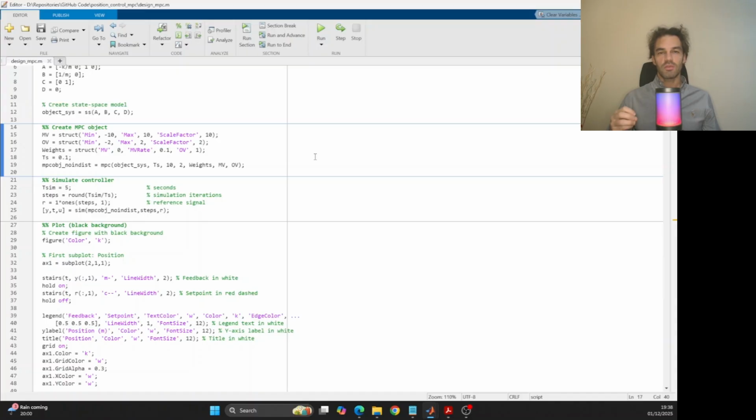But essentially, if you want the manipulated variable to go back, or to preferably go to a certain value once the set point has been reached, you may want to put a weight here. But that might create steady-state error in presence of certain disturbances. So essentially, if you don't need it, generally I prefer not to have a weight on the manipulated variable.